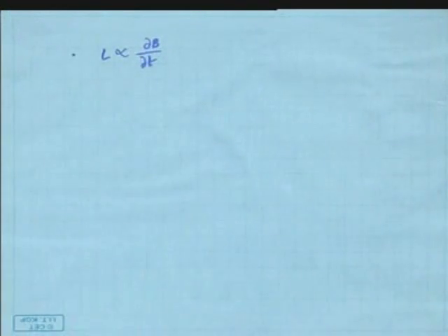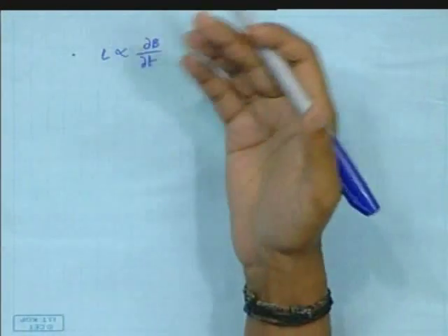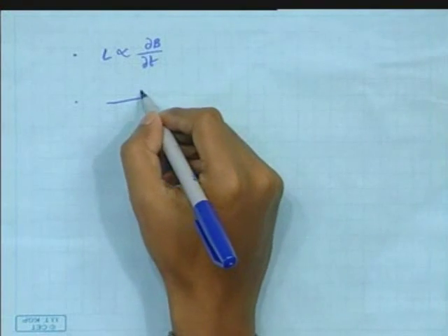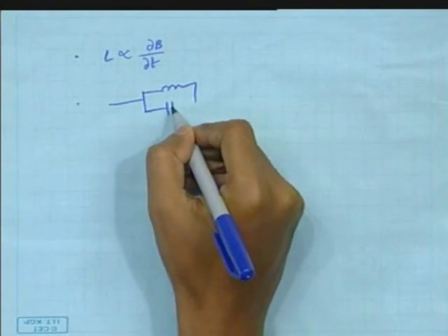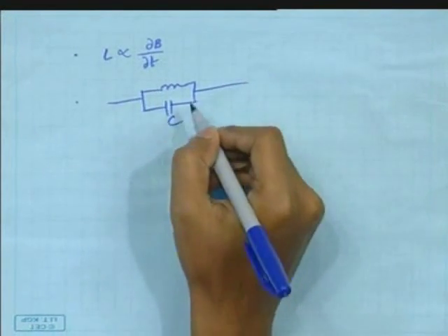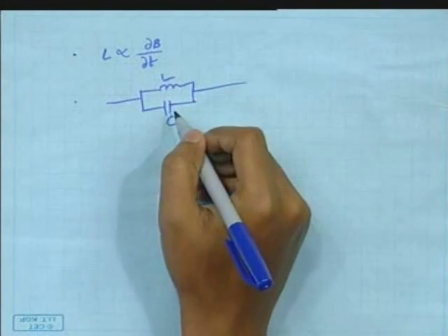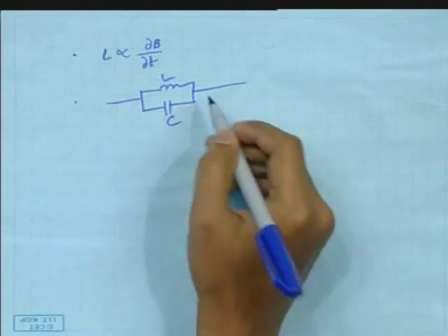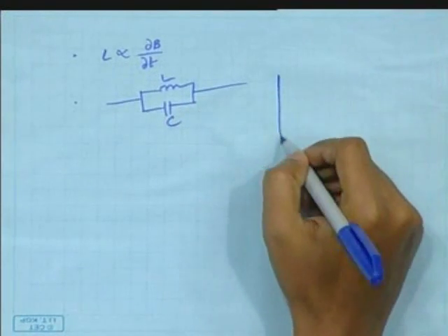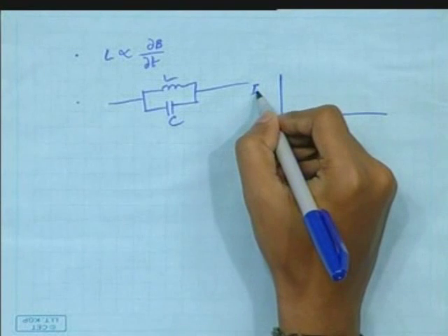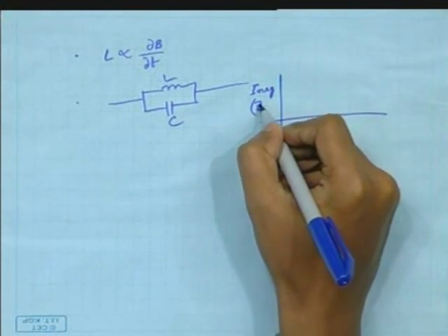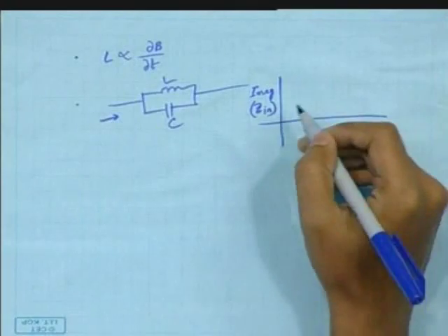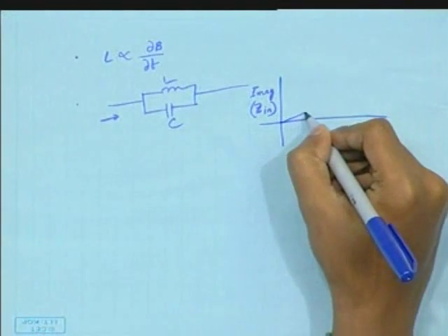Yes, the solenoid one always has a higher magnetic field, hence the inductance value will always be higher in this case. However, another point is that any inductance, as Ashudev already mentioned, any passive as such, is always associated with a parallel capacitance, also maybe a series resistance. Now, what does this capacitance actually determine? At a lower frequency, this will behave as an inductance. So if I plot the imaginary part of the input impedance, looking from this point, initially it will be linear because of the inductance.